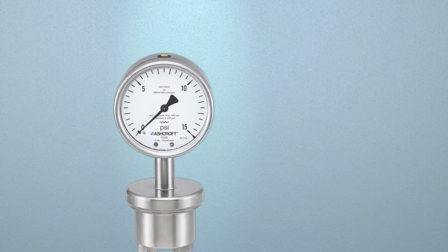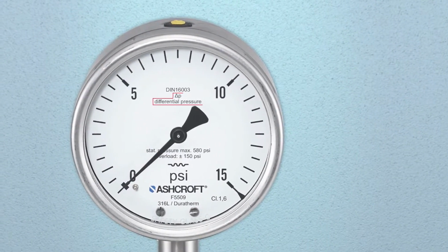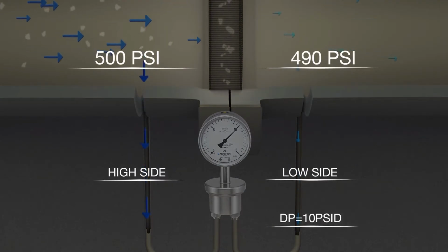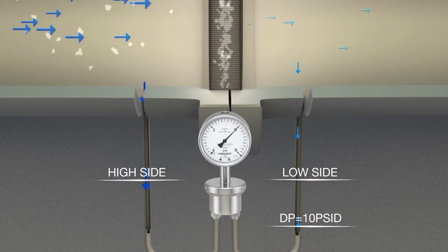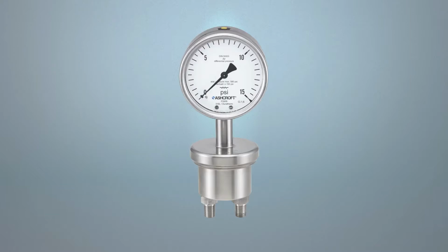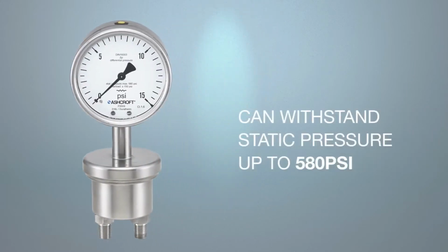When specifying a differential pressure instrument, there are two important factors to consider. The first is the dP range, which is based upon the most difference in pressure that the restriction is likely to produce. The second is the instrument's ability to contain the static pressure, which is simply the pressure in the line. While the differential pressure remains the same, a higher line pressure may require a gauge rated for higher static pressure.